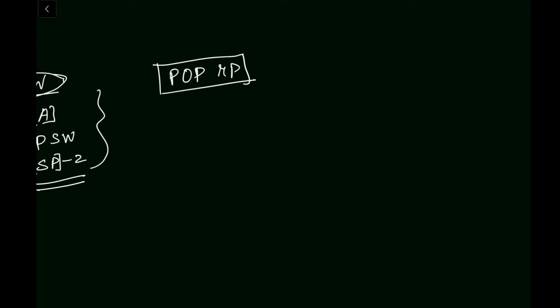Previously the stack pointer content was modified to SP-2. Now whatever is at the stack pointer will be stored into the lower order of the register pair. We have already seen that the register pair is 16-bit, so it can hold 16 bits of data. Therefore, the lower order register data will be modified with the stack pointer content.